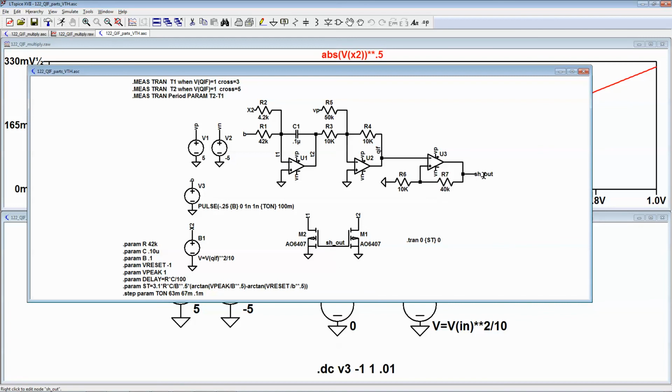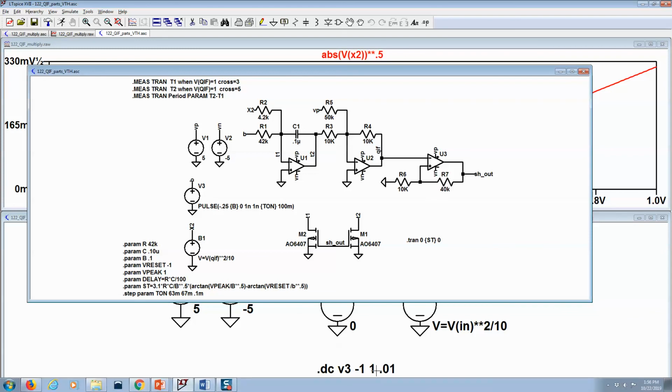So whenever this switches to a high voltage, these turn off, and then it just integrates. When it goes low, these PMOS tie that node and that node to 0, and it discharges the capacitor and resets the integrator. You can just look up resettable integrator. That is how you test the subsystems of your quadratic integrate and fire.